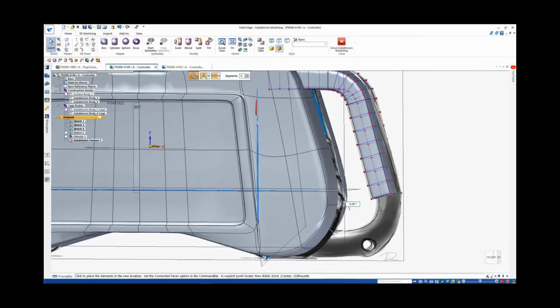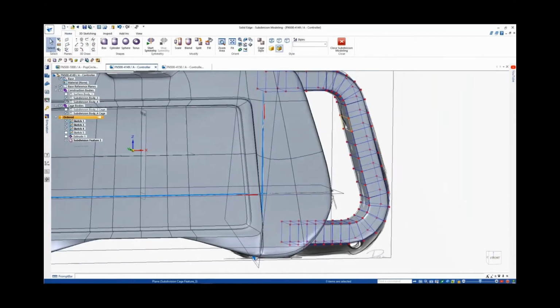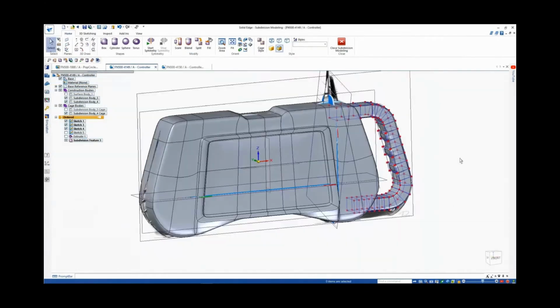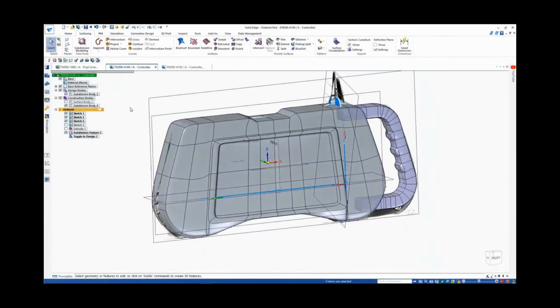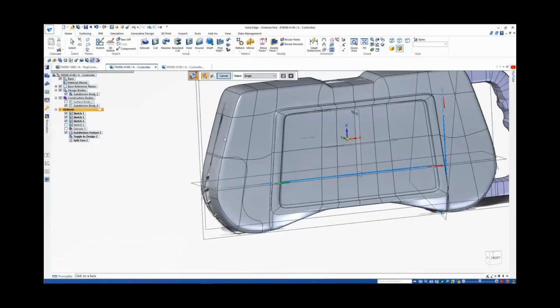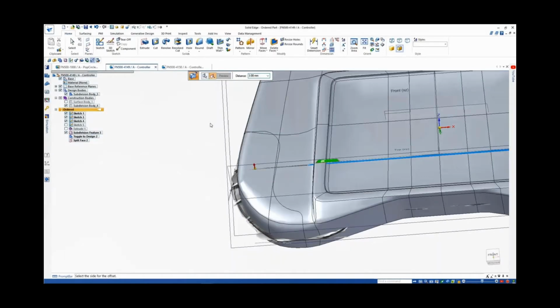So we get the arm, the next radius, and then this shape. And you notice just how quickly that was done. It's important to note that traditional solid and surfacing modeling techniques, they can be integrated. You could use an existing surface to split the geometry and then thicken it to create a raised portion on the handle.